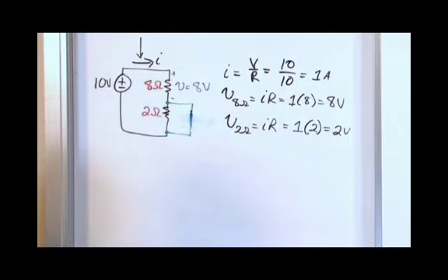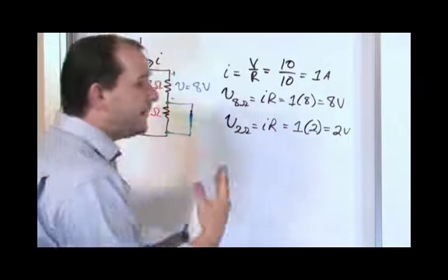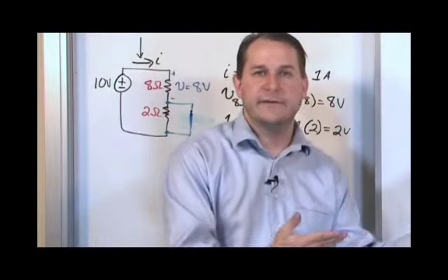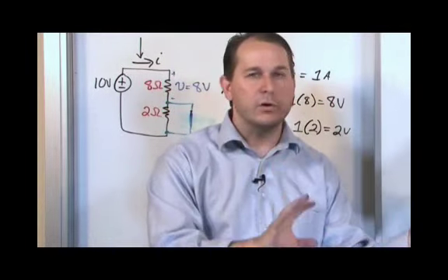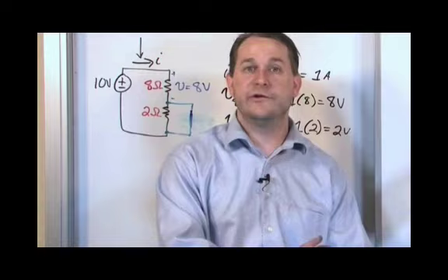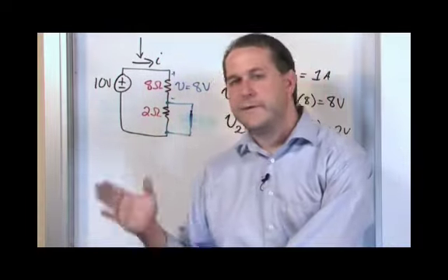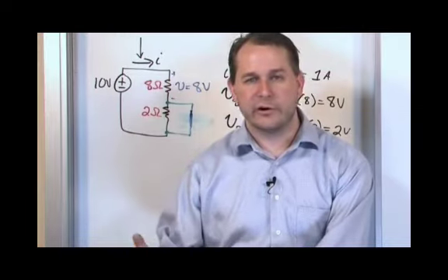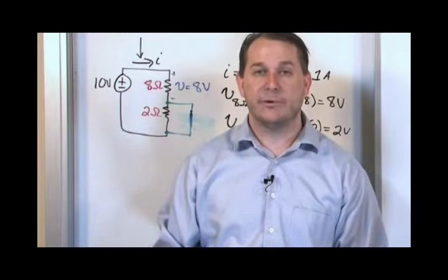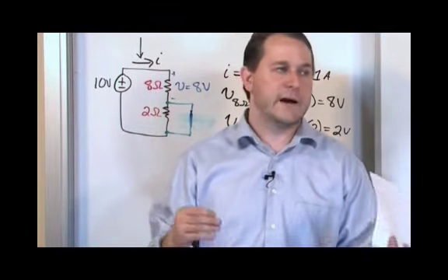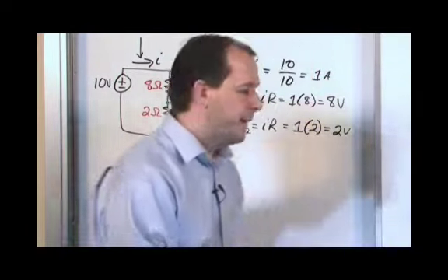There's no voltage drop across a pure wire. So in the limiting cases, super high resistance connected, perfect, don't alter the circuit very much. You're getting what you calculated as far as your no load voltage. Other end of the spectrum, you connect 0 ohms, short circuit, you get no voltage across your output leads and no usable voltage in your load, basically.